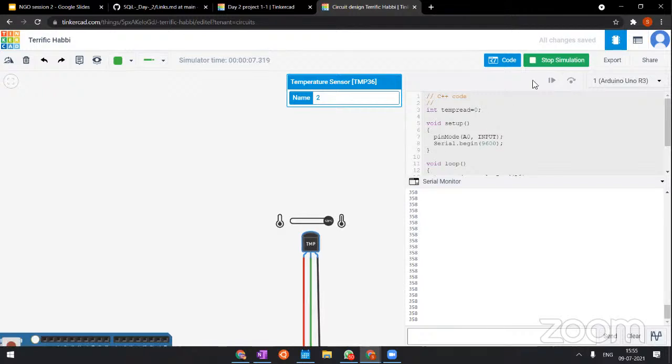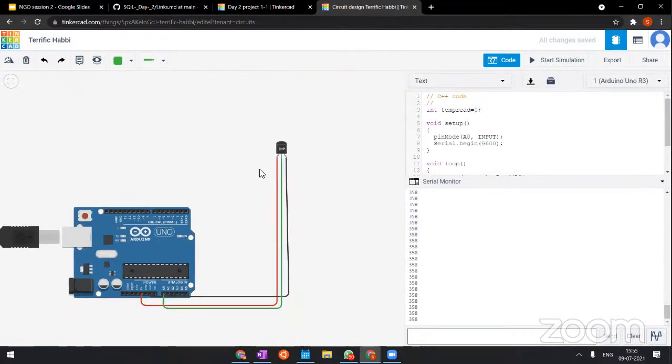Right. So now that we know the lowest value of the tempRead variable and the highest value of the tempRead variable, we want to be able to find out the exact temperature, right? So basically what the analog pin is doing is, I'll just go ahead and type it down here as a comment. When the variable tempRead is equal to 20, then the actual temperature, I'll just write it as temp, is equal to minus 40, right? And the next statement is when tempRead is equal to, say, 358 at the highest value, the temperature measured by the external temperature sensor is 125.